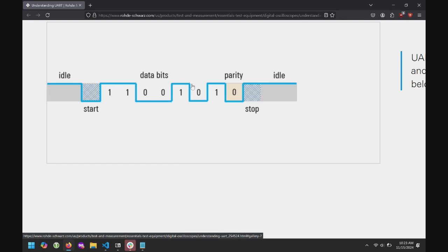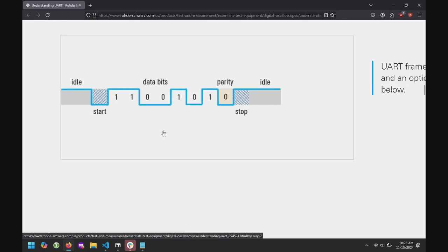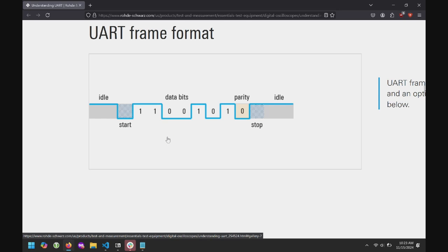Okay, yeah, what do we do? Yeah. You have a preset. Exactly. Yeah, perfect. So ahead of time, you will predetermine what clock rate you agree on. Both your transmitter and your receiver will be intentionally running at a very specific clock frequency, and this is called the baud rate. The baud rate is usually pre-specified, and if you've ever used Arduinos and serial println, then you will need to specify the baud rate in order to make sure that your computer can communicate with the Arduino over UART.